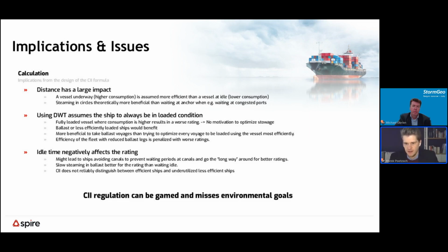So if a vessel is staying for long periods in anchorages or in ports, that will negatively impact the CII rating, and might also lead to unintended consequences, where owners or charterers will decide to change routes, using a longer route instead of going a shorter route and maybe having to wait in an anchorage, to achieve a better rating without actually achieving any better emissions or any higher efficiency of the vessel.